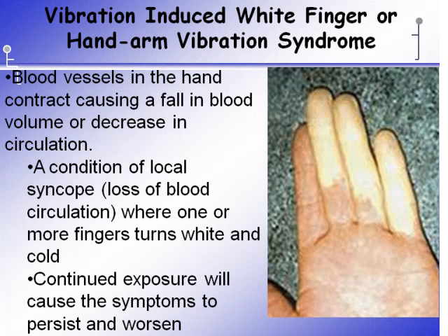So when the tool is vibrating in the worker's hands, it stops the blood from getting to the ends of the blood vessels. So you have this drop in circulation and this drop in volume. When you start to have the blood vessels dying off and a loss of circulation over a long period of time, not just the period of time in which you're using the hand tool, then the fingers turn white and you actually have the loss of sensation. You can have thickening of the fingers in this particular area.